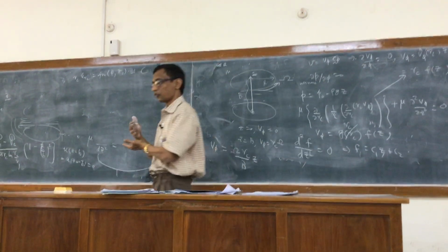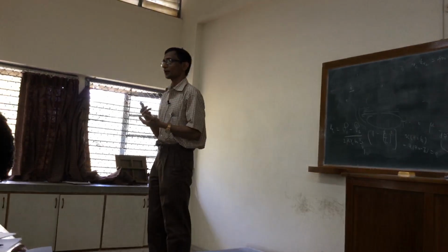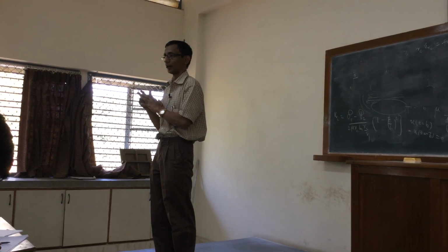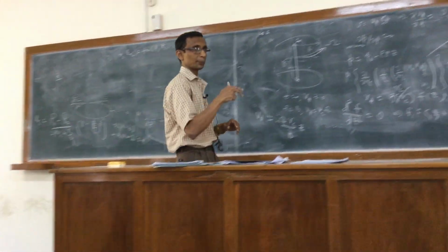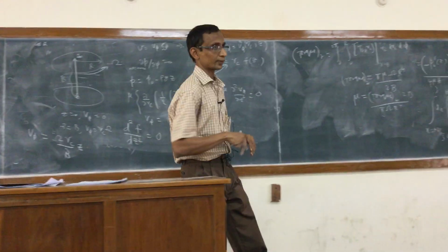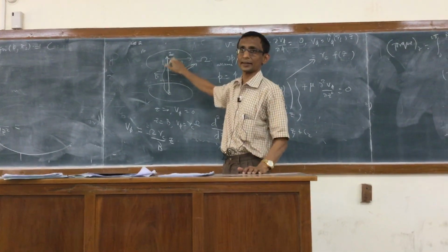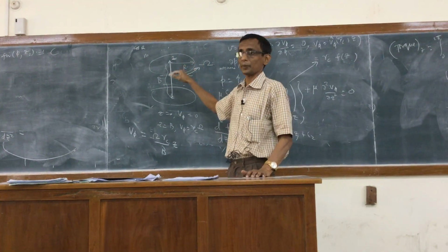This is again a flow of a fluid between two cylindrical shells, but it's a radial flow. So it is sort of complementary to the earlier case where we had the cylinders being rotated with constant angular speeds and dφ was dominating, and the case of two parallel discs, where there was a radial flow. So these two problems are complementary.